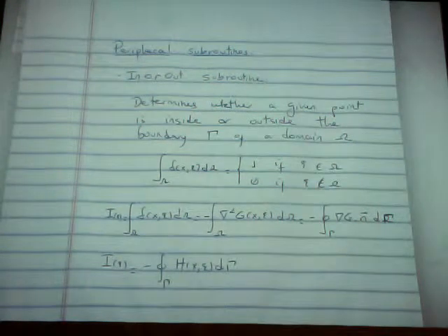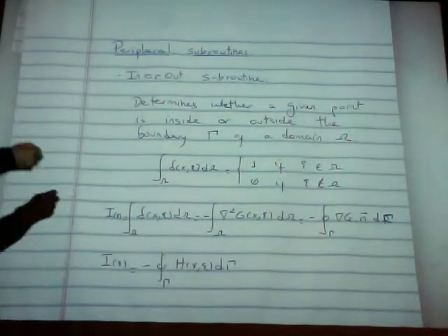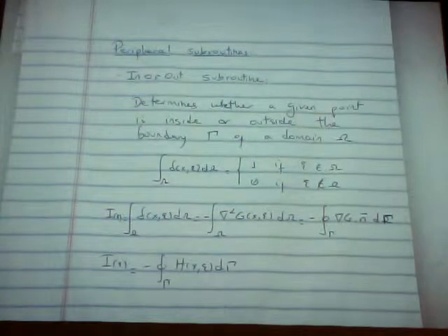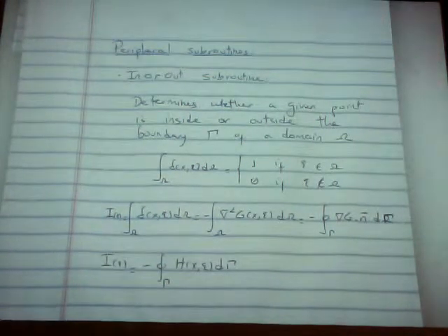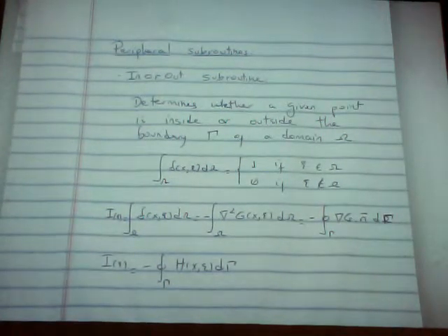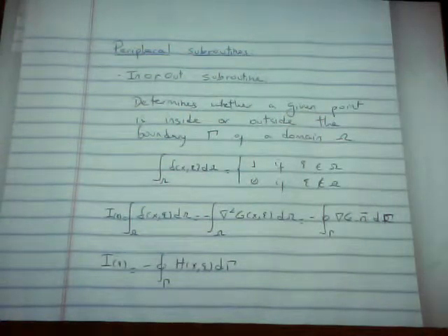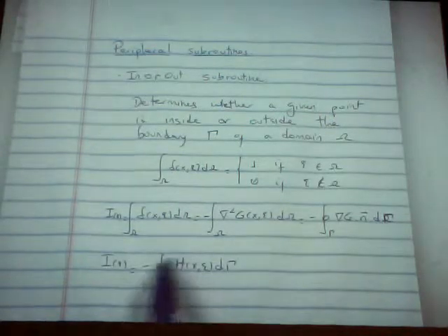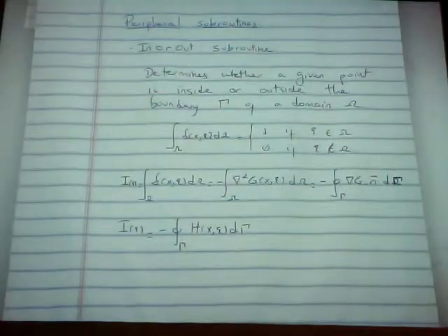So all you have to do is take the function h, which we already have because we need it to generate the influence coefficients, and integrate it around the boundary elements, and this integration I approximate. If you get 1, that means it's inside. If you get 0, that means it's outside. Okay? So you basically use the same boundary element discretization that you have.